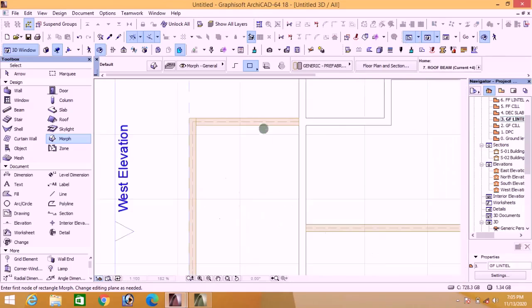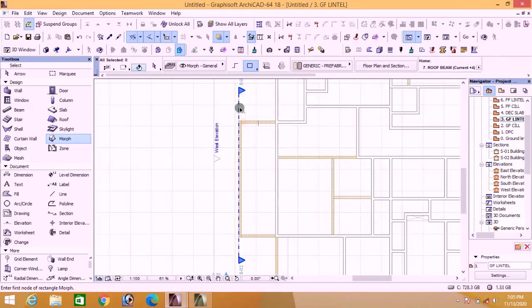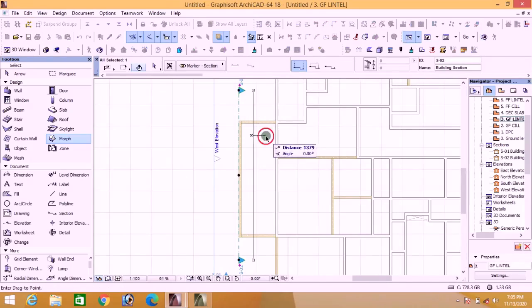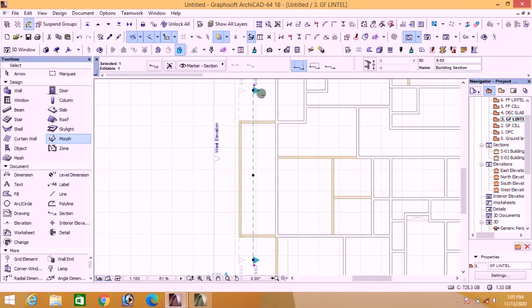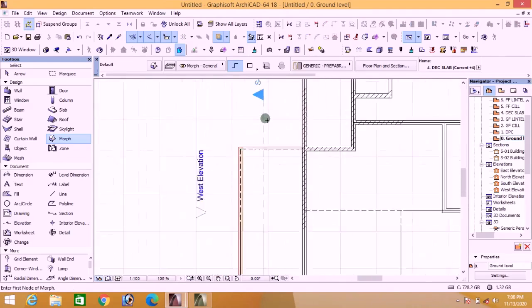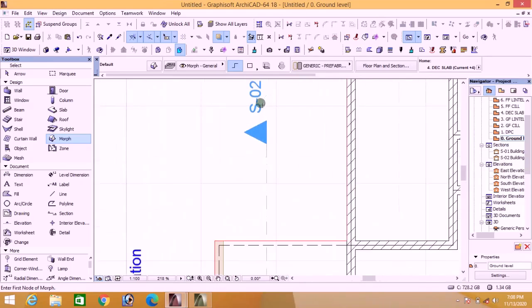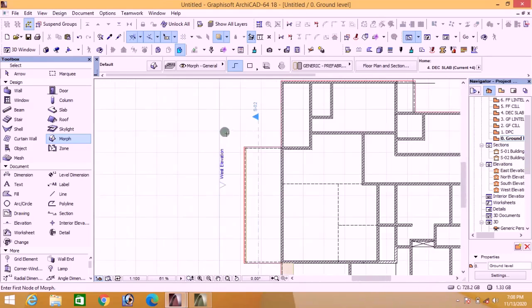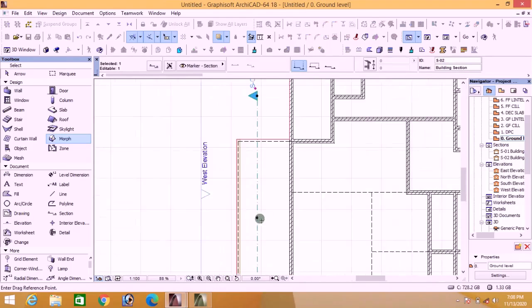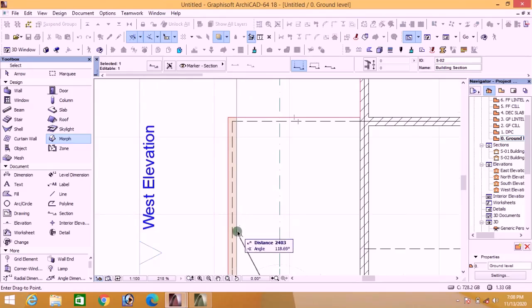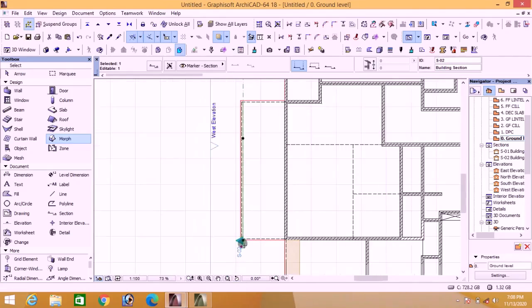Go to your floor plan. Bring this section into this place. Change the direction of focus of the section with your Ctrl M. Click on Ctrl M. Then hold it on this center. Now the section is now pointing towards this side. Now having changed this section 02 to be focusing towards this direction, drag it close to the wall. At this spot, drag it very close to the wall. Lap it on the wall surface there. Stretch it beyond this place and open it.